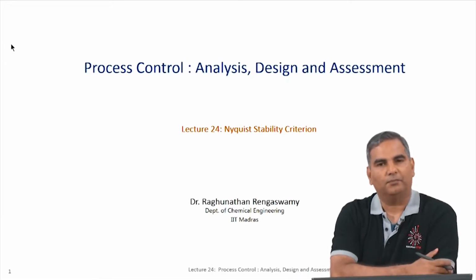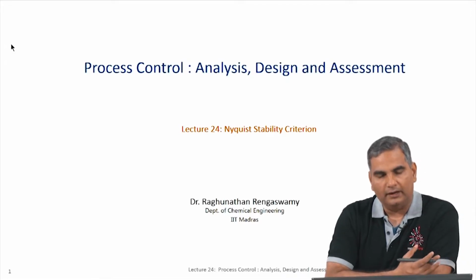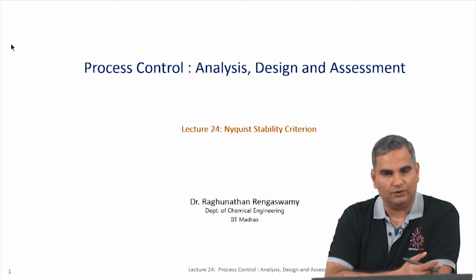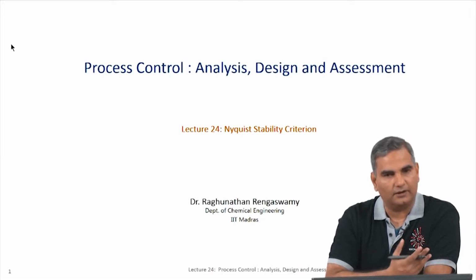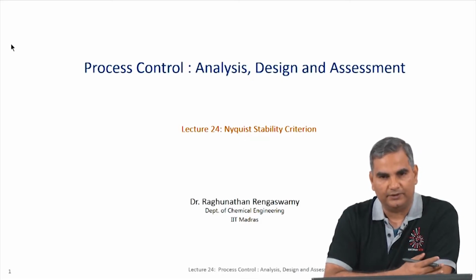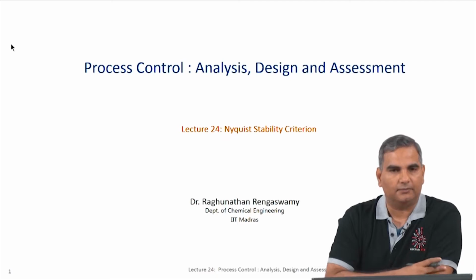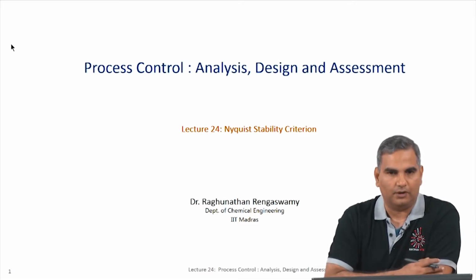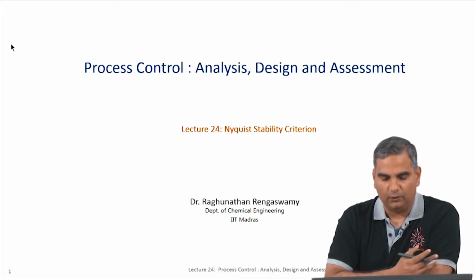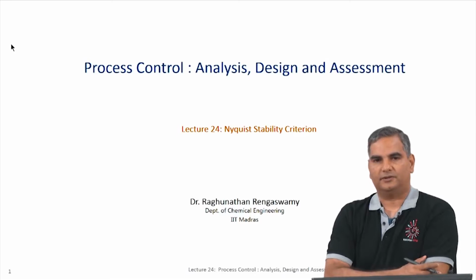This is particularly important because we will have a G desired which by design would be stable. So, for the nominal system, that is if the model and the process have the same transfer function, the closed loop system is going to be stable. However, the real challenge is to think about what happens when my process is different from my model. So, will the stability idea still hold, and we will see how to analyze stability of systems with time delay.